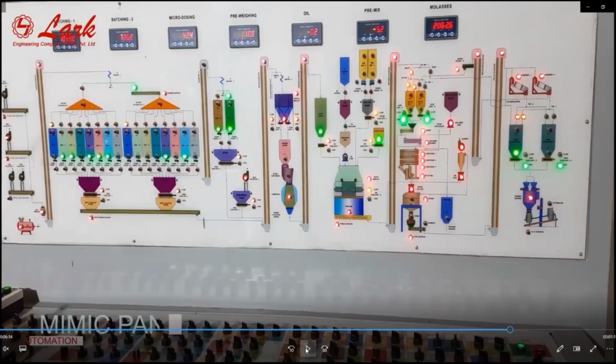Like if we run the hammer beaters for more than their specified life, the corners of the hammer mill beater become round after some time, and due to the round corners the texture of the feed changes, and with the changed texture and coarseness, there is more recycling, less conditioning, less steam and moisture absorption, and poor PDI, and more recycling would be there.